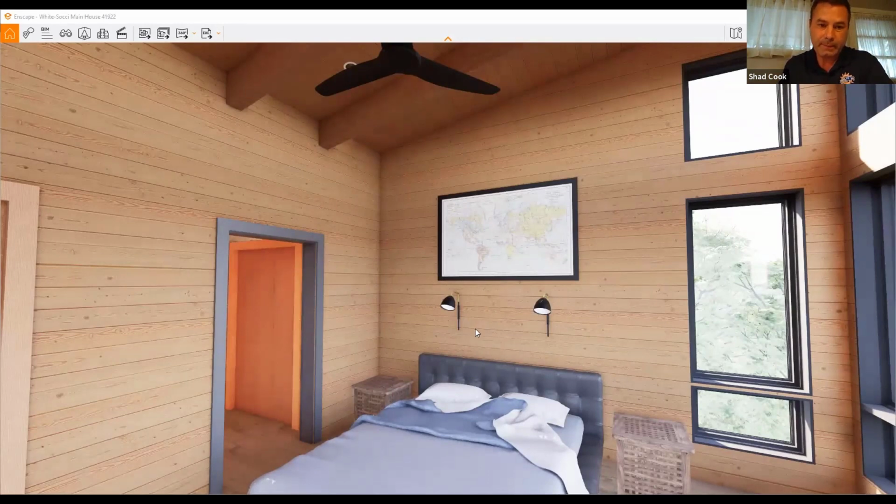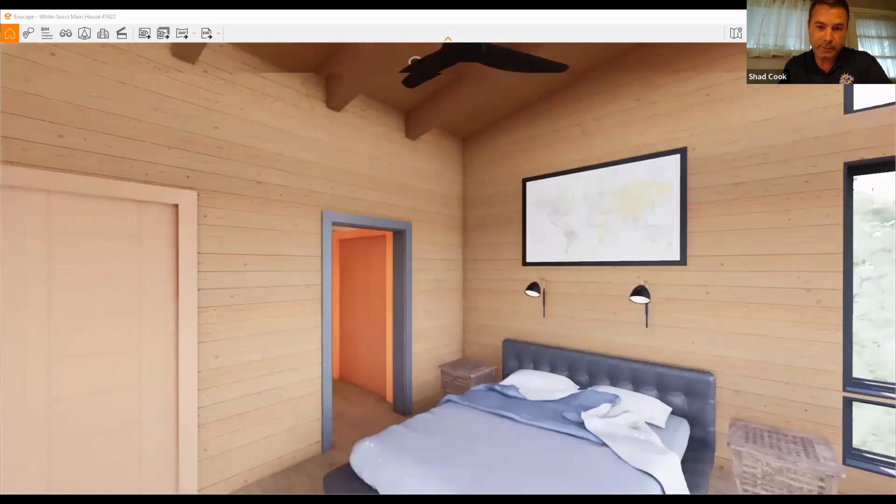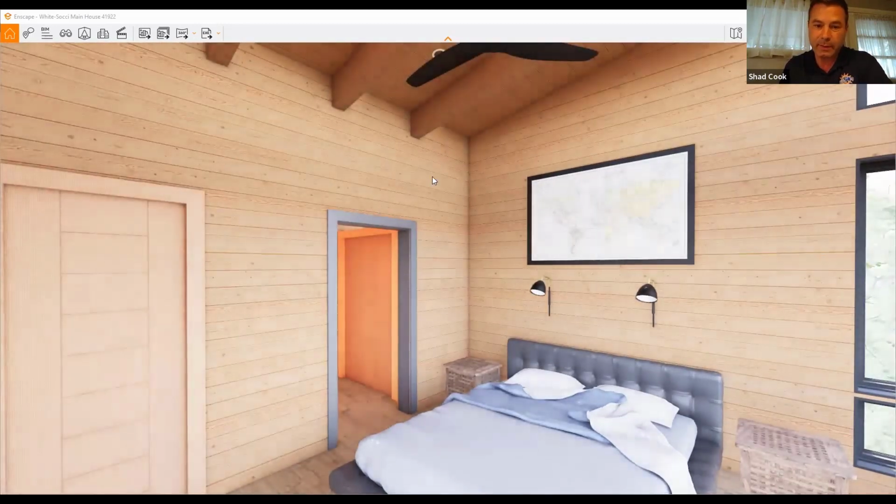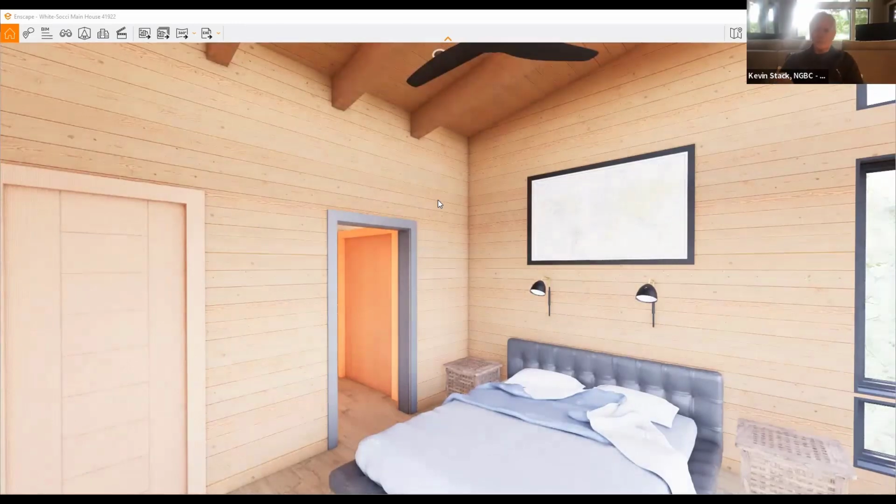Sure. But then coming up to serve the bedroom, so trying to get air to the bedroom, throwing air from the floor in a corner of the bedroom is obviously not ideal. You can only do so much with directing the airflow, but if we were able to get a sidewall. So what if you went up high, Matt, and then went right across the backside of both those closets?